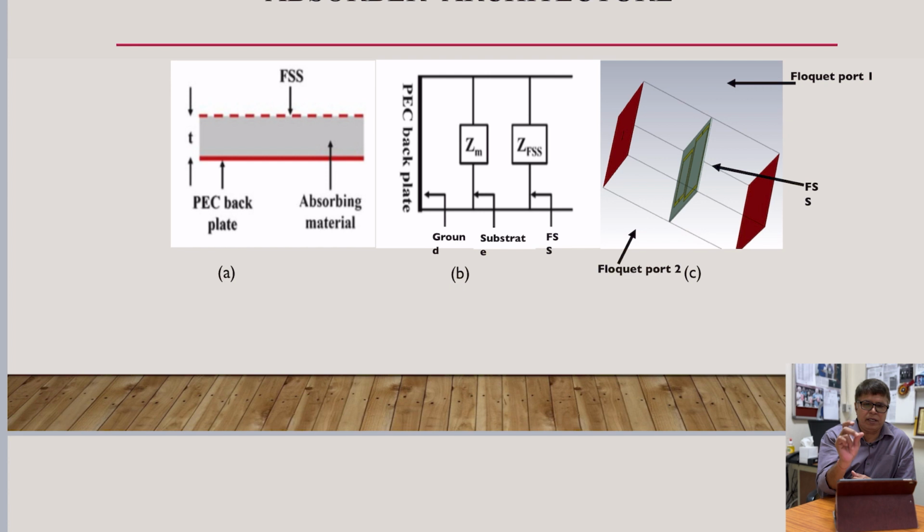An electrical charge will get accumulated on the structure, that is the FSS, which is also known as SRR or ERR, and will be frequency specific, meaning these are designed for a particular frequency. In our example, these are designed at 2.4 gigahertz or 1.6 in case of GPS frequency. So these are also termed resonant surfaces.